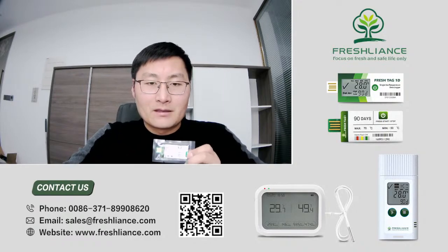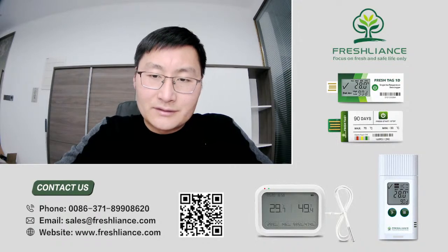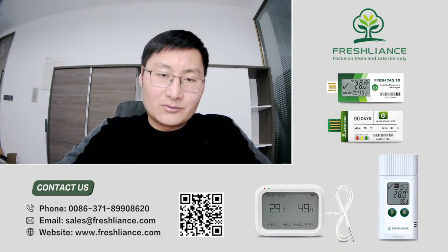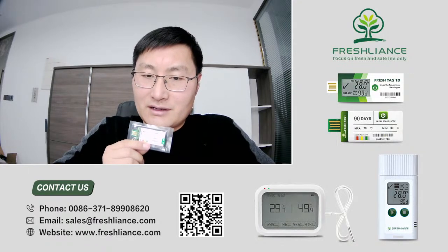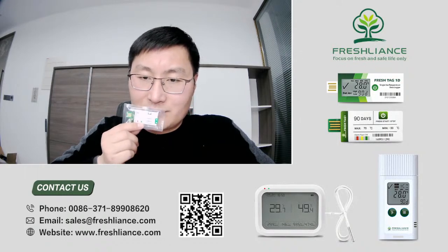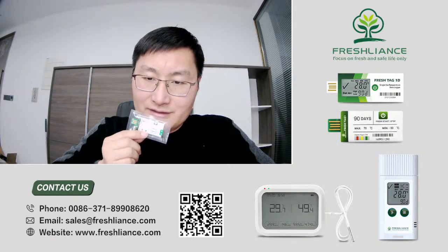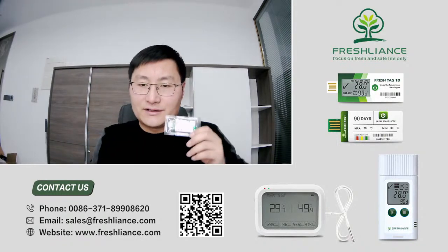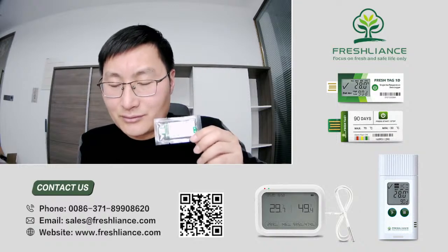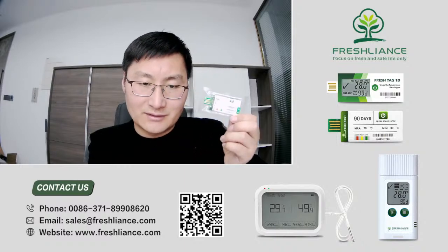And in alarm, red indicator flashes 3 times. Data logger stops recording. Red indicator flashes every 30 seconds. It means alarm status. Red indicator flashes every 30 seconds. It means data logger works at alarm status. If data report is generated to computer already, after connecting them, the red indicator will flash once.